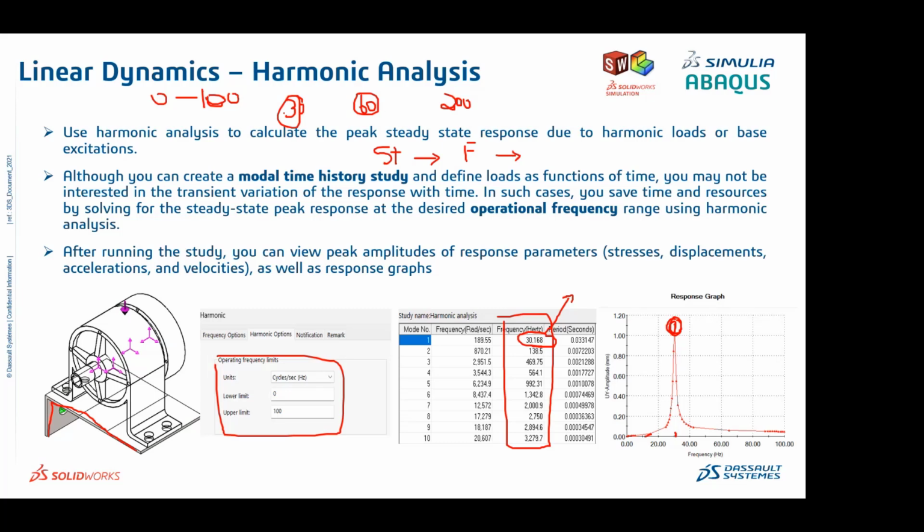if it is a shock load impact kind of thing, or during transportation there is an acceleration happening, right? These kinds of inputs, where you can give load with respect to time, are a time history analysis. If you have the operating frequency, you can straight away perform a harmonic analysis for the loading condition, and you will see across these frequencies where the highest stresses and amplitudes are going to come.